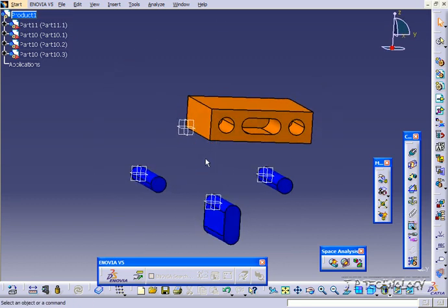Now with this tool, personally it's my favorite one for creating positional assemblies. It's really quick, really easy. It works like the other ones, where the first one that you click is the one that's going to move. So you click this one to move it into this one. And it allows you to quickly and easily snap components in, bring everything together, and create a positional assembly. Now saying that, you also have to work around the snap feature in certain situations a different way to get the results that you want.